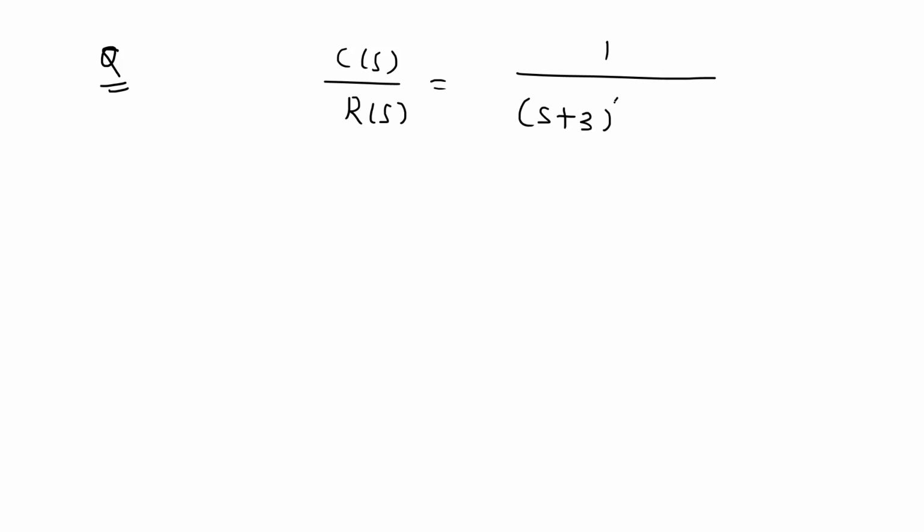Whenever you solve a time response question, we are always interested in the denominator part, because from that we can find the stability of the system, the peak overshoot, delay time, settling time, all of this. So look at the closed loop denominator: (s plus 3) whole square plus 16. Make it equal to 0, because this is called the characteristic equation.